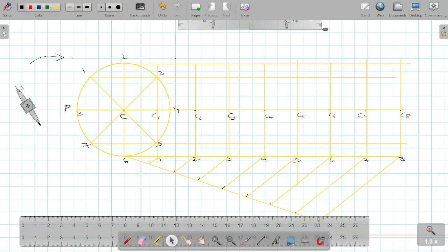circumference of the circle. So for that, I have already given you a hint. When P tries to move up, we will make the cuts or the arcs on the left hand side. Whereas when P tries to move down, we will make arcs on the right hand side. So following that, first we will keep the compass at C1 and radius same as 35. We'll do the marking on the left hand side now because P is starting by moving upwards.